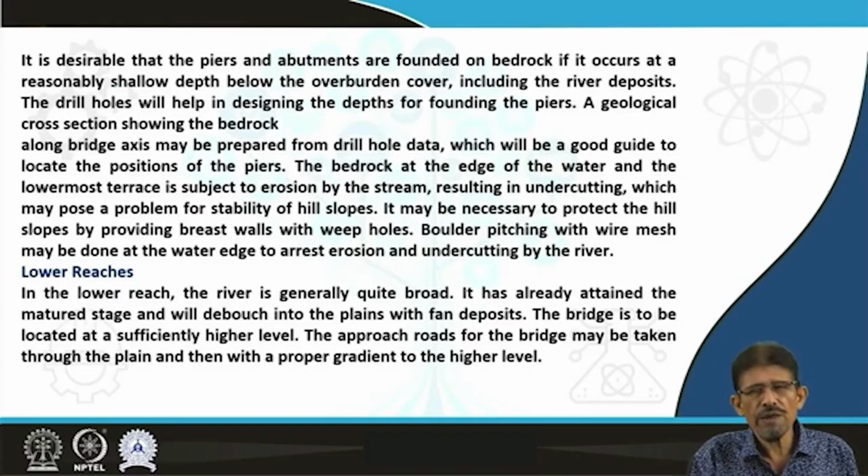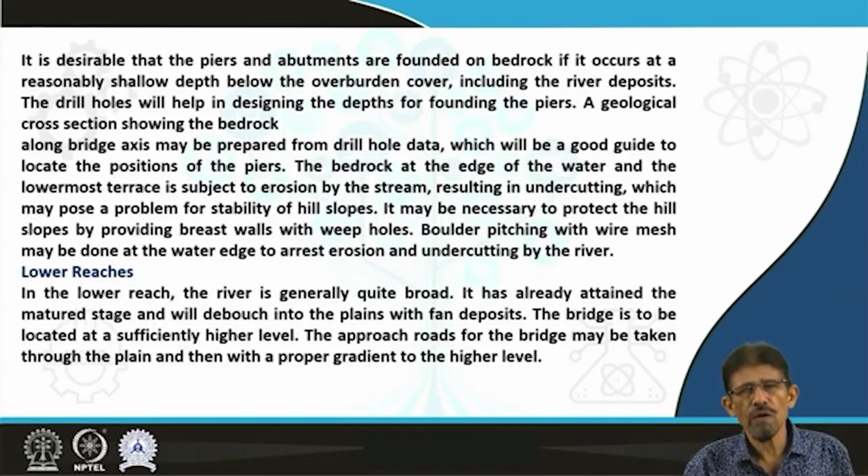We have already discussed the strata or layers located at different levels. So for the upper reach, the rock exposures are available which are sufficiently strong and of high quality that can bear the load of superstructures. Due to narrow valley, this type of region requires a single span bridge, which is not heavy in comparison to a multi-deck or multi-span bridge.